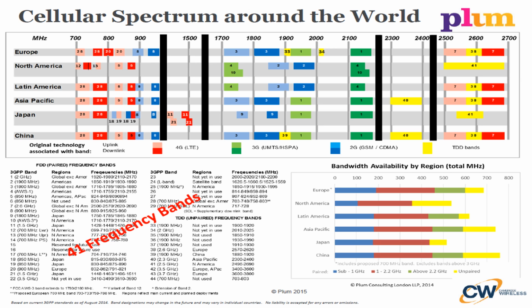Similarly, you can see most of the world has 3G on 2100 megahertz, the one in green color. Of course, some other frequencies are being used for 3G, but the most common frequency for 3G is 2100 megahertz. That's why 3G was quite poor in penetrating indoors. When you were indoors, you might receive GSM but not 3G, because the frequency was very high.